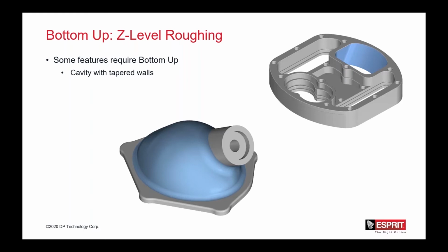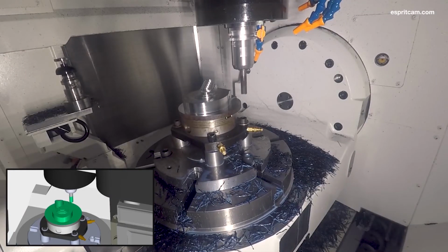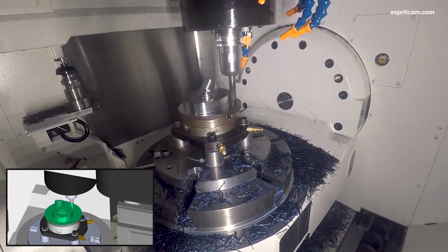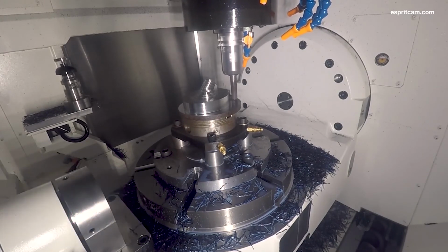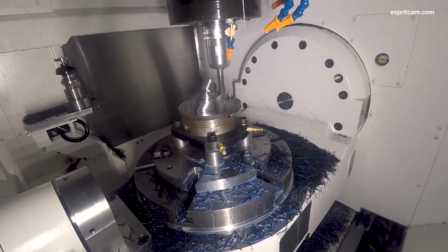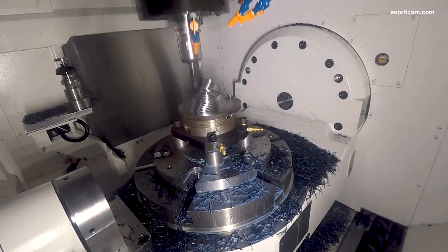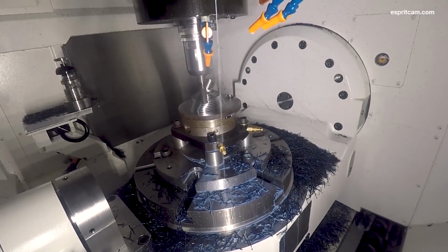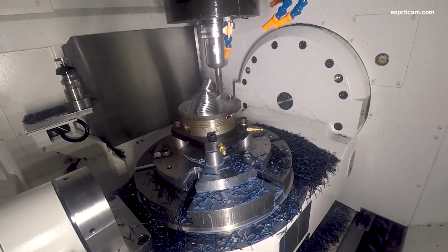That's where your advantage comes from with the ESPRIT. We don't recommend doing a traditional top-down milling. It's always bottom-up roughing is much better. And I'll go ahead and show you a video on that. At incremental depth and working its way from bottom to top. This is the concept of bottom-up roughing.